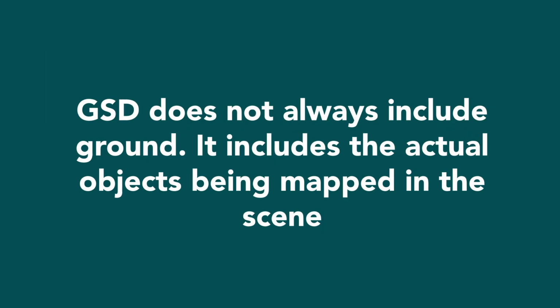And one of the key concepts that we see attached to this is essentially the overlap between two images on the roof for a roof inspection job. What happens is that a lot of people think that the ground sampling distance is actually with respect to the ground, but most of the time the software is calculating this with respect to the roof or with respect to the surface that's being seen by the drone image. So the key concept here is that ground sampling distance does not always apply to the ground. It applies to any surface that can be mapped by the drone. And once again, it's actually the footprint of every pixel in the drone's image on the ground, which I'm showing in the illustrations here.